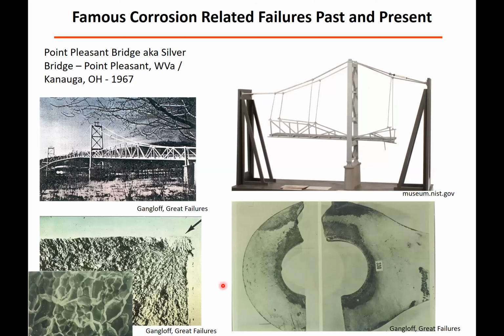Here's a more local example. Similarly, you can see corrosion pitting that occurs, and so the failure of this bridge was also due to environmental assisted cracking from the corrosion pitting that nucleated the cracks.